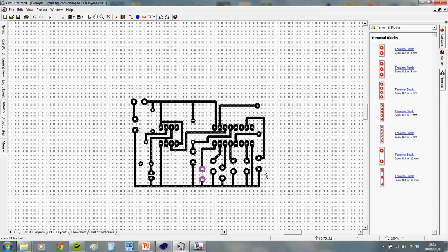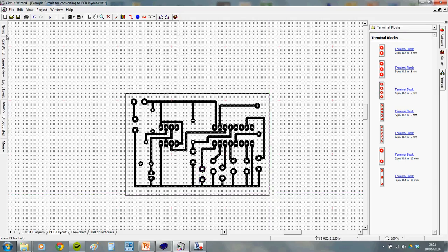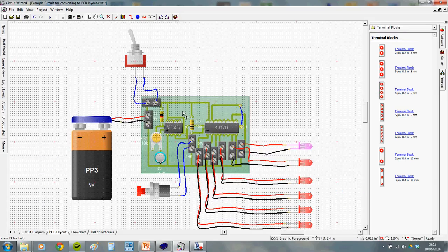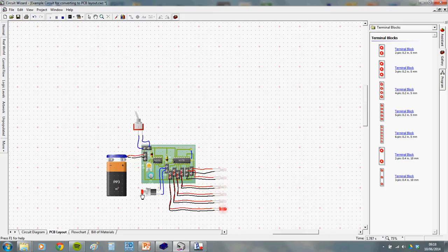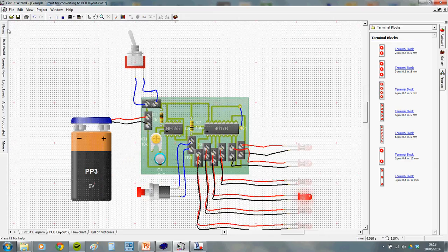Right, so we're going to use the border and label tool now to spice this up a bit. First we'll do the border. If you go up here and click Circuit Board and just drag a rectangle around your object, that gives you a nice border to it, and if you go and look at real world view now, you'll see it's actually put a background on it. Okay, so that shows you where the limits of your board are for when you're sanding it. Let's just check those LEDs work. Yeah, all fixed.